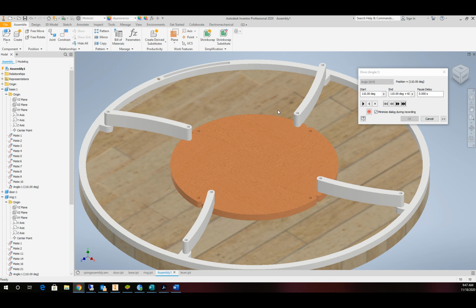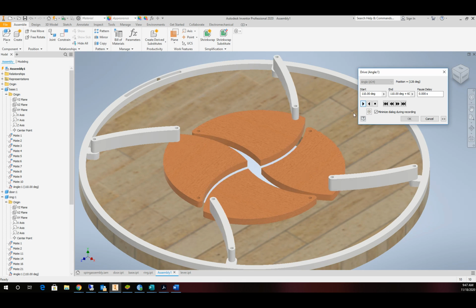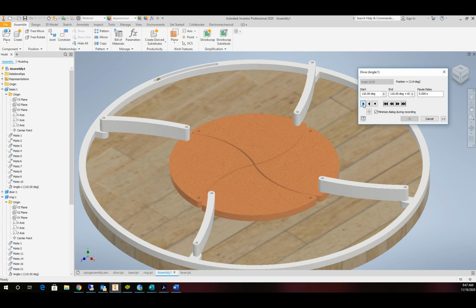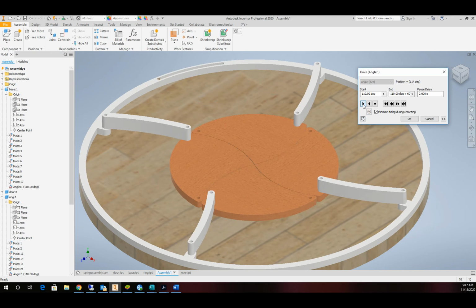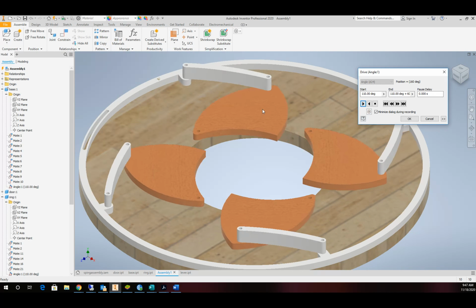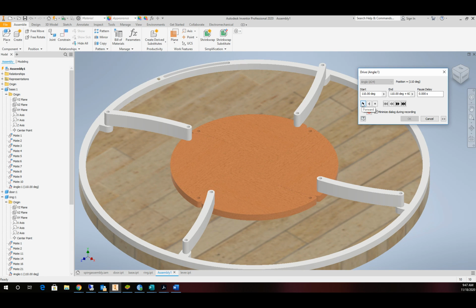Today we're going to use Autodesk Inventor to make a 4-blade aperture, or kind of a futuristic gate. We'll take a look at it finished, and then we'll make the parts to make this work. It's fairly easy. It's just a linkage problem, but it has a dramatic impact, and we're just using some standard drive constraints to accomplish this. I'll do a follow-up video and put this in Dynamic Sim in order to make it function properly, using joints and some other features.